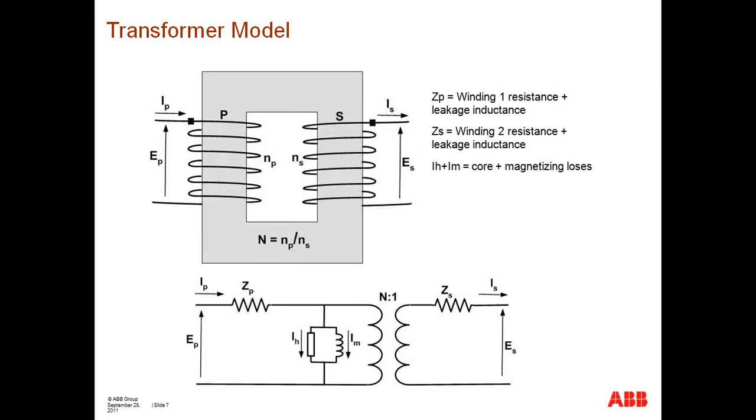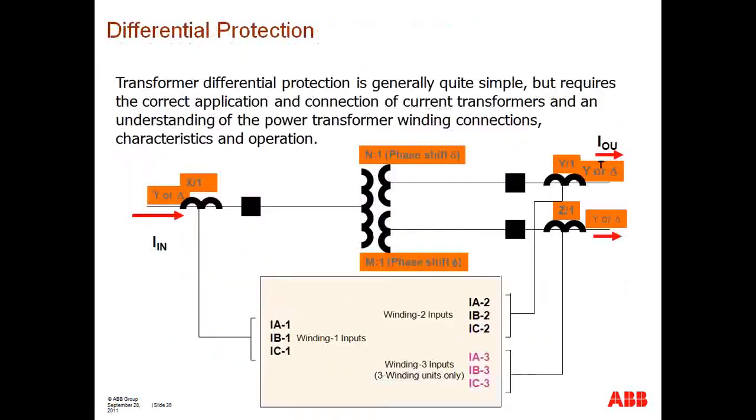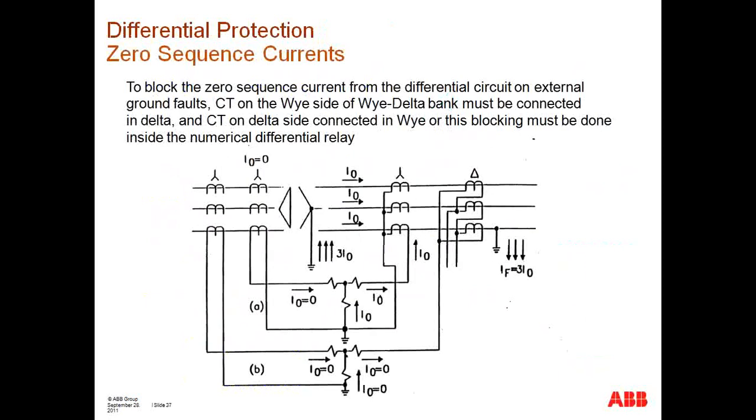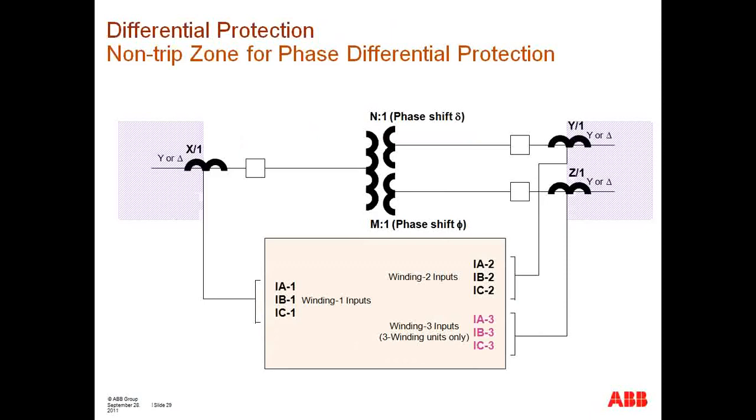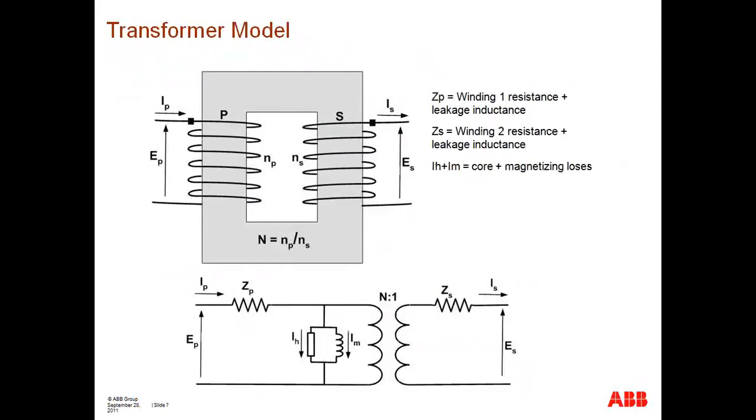So a big part is your source impedance. It's obviously what for the most part is going to regulate what that inrush current is, along with the point in wave, which is random. Now, if the question is more in regards to the amount of second harmonic content, that is really something that the manufacturer of the transformer needs to provide, because that's primarily a function of the material and the type of construction that was utilized on the core, which in turn is the primary parameter that affects how this branch behaves.